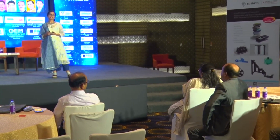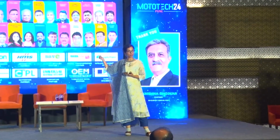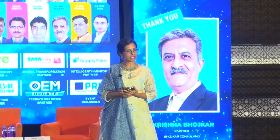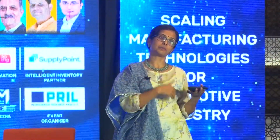Yeah. So when I say having lighter parts, it means applying the principles of topology optimization to a certain part. For example, the IIT Bombay project that I showed you where the part was much lighter, right? So what we have done is that we have not reduced the thickness from 10 to 5 as is, but rather we have only retained material along the stress path based on the loading condition and the boundary condition, so that the part functions as it should, but it doesn't have extra material that is not necessary because it's not load bearing. So by applying those principles, we are able to lightweight.